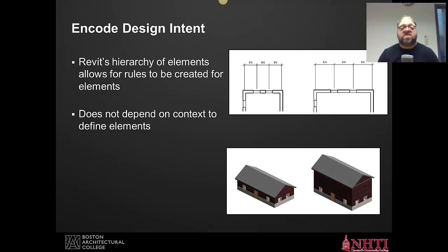No. But most of the time, maybe 85% of the time it does, maybe even more than 85%. So it'll ask you, do you want me to connect these two elements? So you can say, yes, I'd like those two to connect. So then the wall will fill into that gable end instead of just being flat across the top, and it'll also be now connected to that roof.